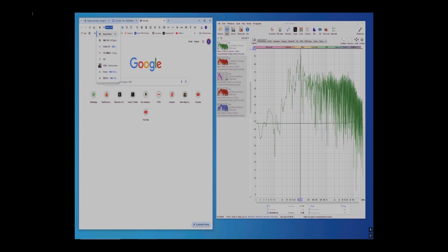And one last warning is double check your amp assign configuration after the filters are transferred. Make sure that it's the same. Because especially with external amplifiers, I see that my pre-out fronts switch to pre-out rears randomly. And all you have to do is switch it back and then it will work. And this is also valid for the cases where multiple subs are muted. You just go turn them back on. Hopefully all these problems will be sorted very soon.